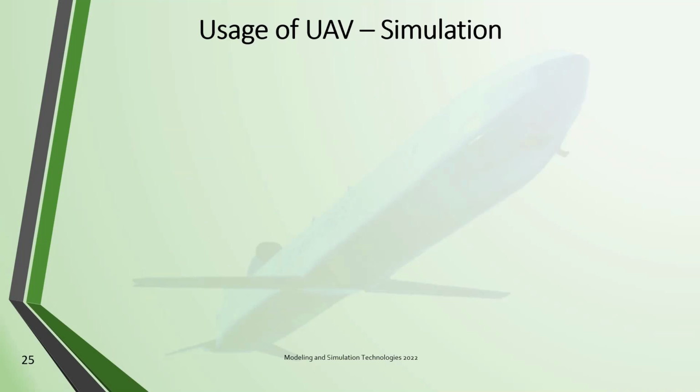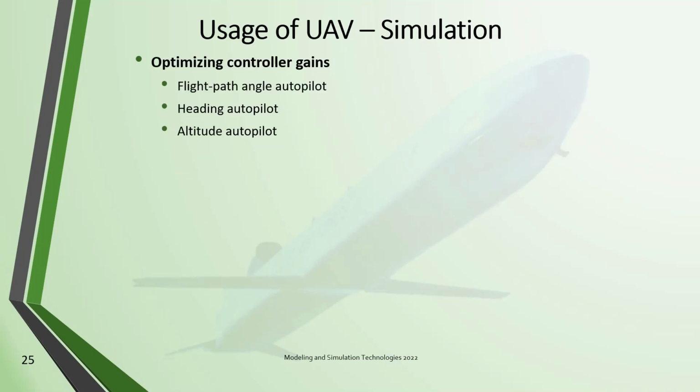So what is this UAV simulation used for? Well, the students will use it to optimize the controller gains in these 3 autopilots. Now, these autopilots may have been designed using MATLAB particularly to get the right gains, but this analysis would be just a linear analysis. Here in the simulation, the autopilot has to be validated with the nonlinear dynamics of the vehicle itself.